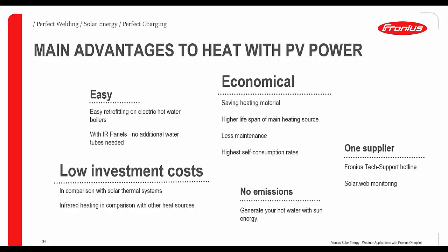Then there was another question which is, I think, very important too. It's about the heating rod which can be used. If you use a three-phase heating rod, make sure that the heating rod is supplied with 230 volts, so you need a neutral connection as well. The heating rods must be connected in a star.